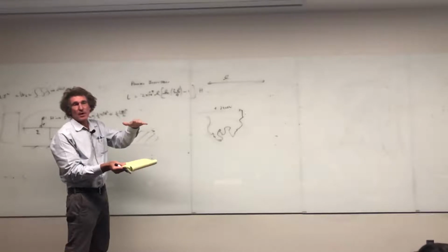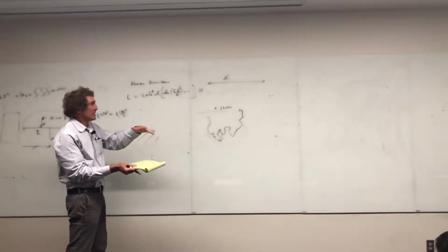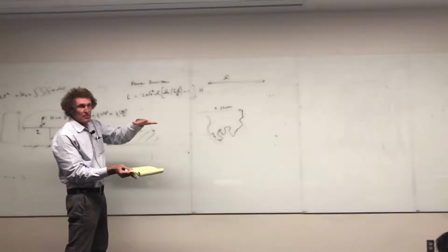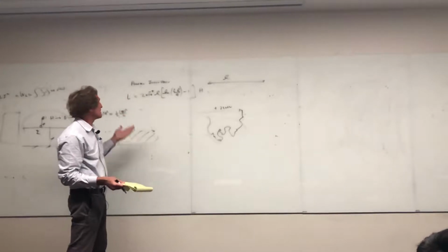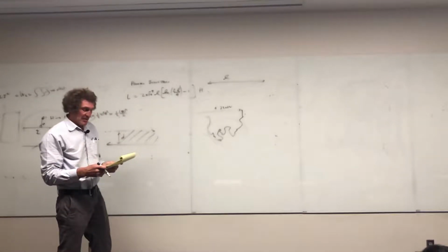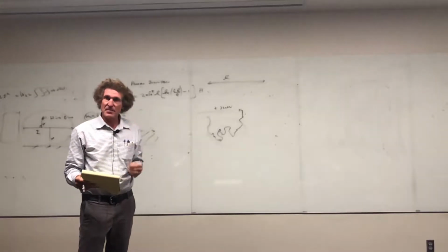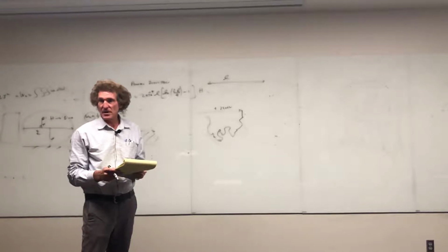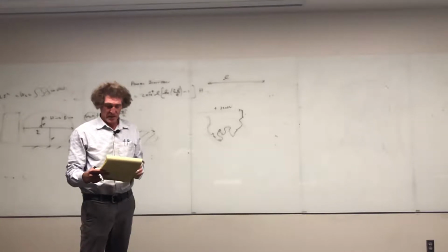Consider it above a ground plane by a distance of at least, say, 5 radii. This will give you an estimate, but it's very hard to calculate. I've never read the entirety of this, but partial inductance is something you use a lot of times when you're building things to get a first-order guess at the effect of the inductance of a line.